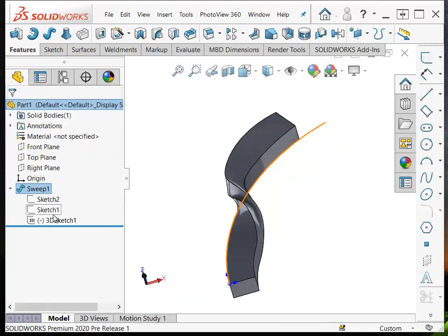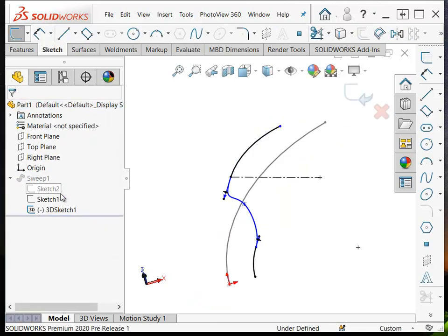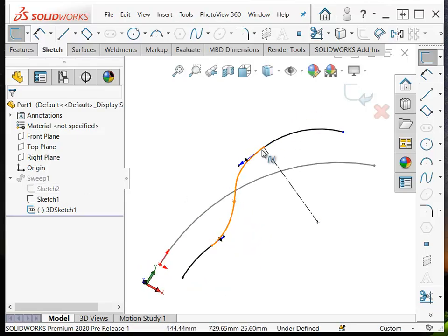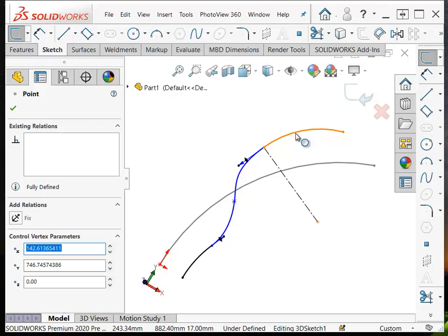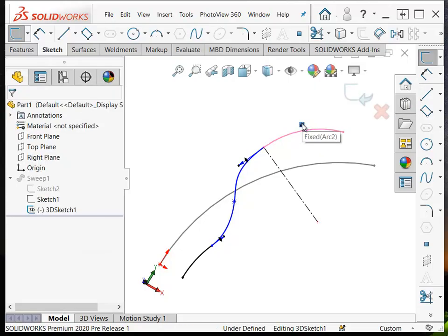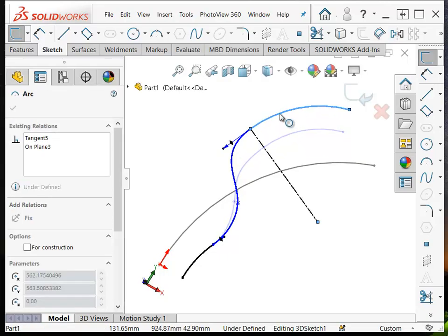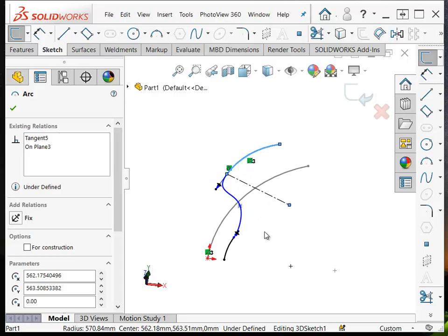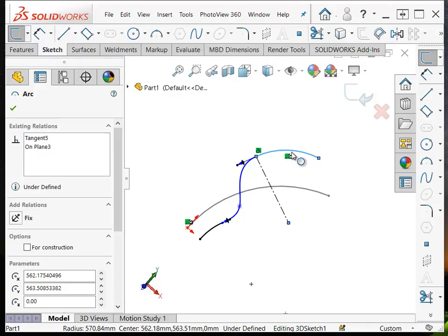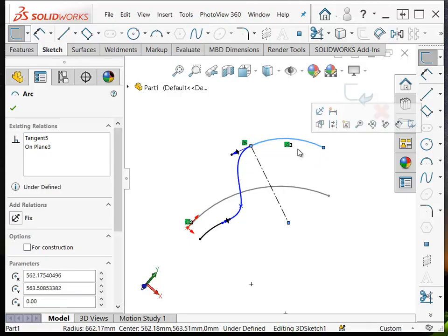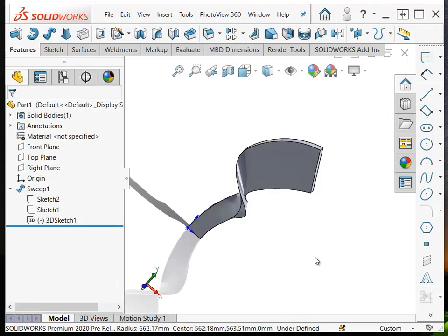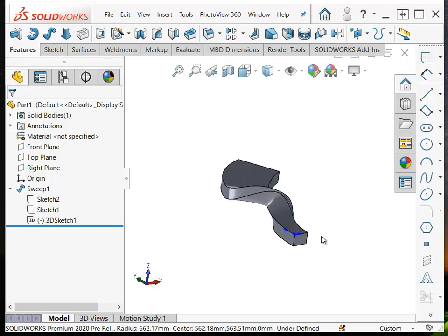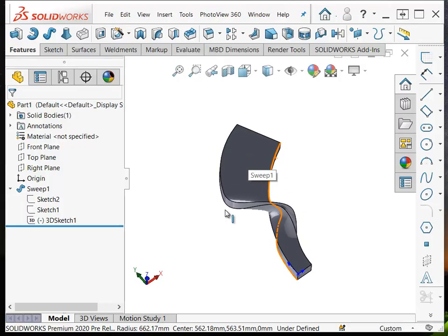And that's pretty cool. So if we go back here into this 3D sketch and remove a couple of relations that I created just to lock it down. I used the fix constraint here a couple of times. I want to enlarge this a little so that we demonstrate a little more how much control you have over the size and the orientation of the sweep profile. Okay, now you see over here, it's become much larger.